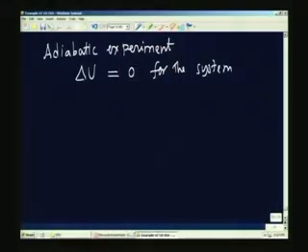There is also some amount of heat released by the wire when it initiates the combustion reaction. For accurate determination we have to take that into account also. However, I will not introduce it in this simple discussion because it is not going to change what we are discussing too much, it is just going to add a small value. So, there are two things: the reacting fuel which has undergone a change because of the reaction, and the rest of the vessel.